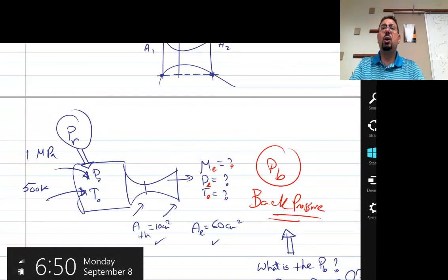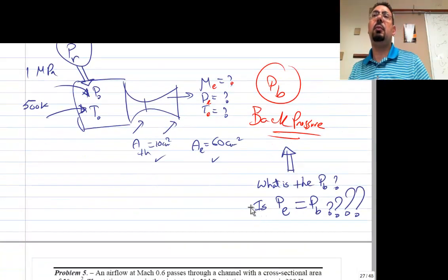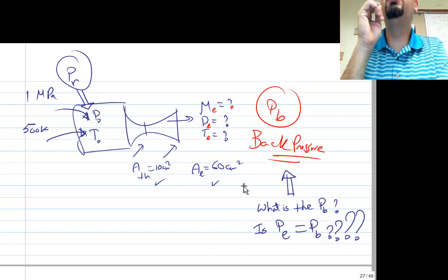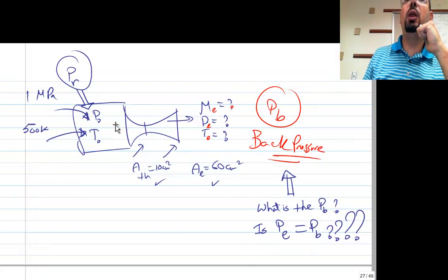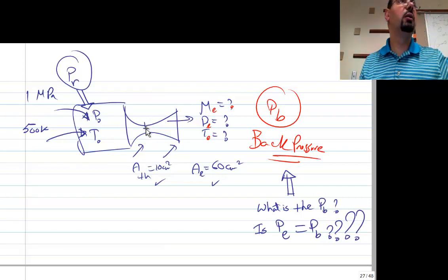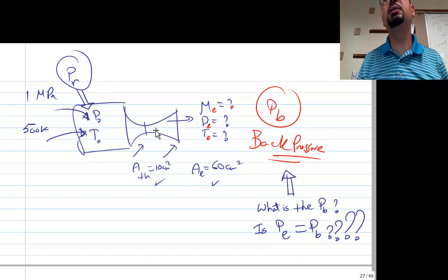Right. So again, now we know that the flow will accelerate into something like this, and once it reaches the throat, will it become subsonic and decelerate again because the area is getting bigger, or will it hit Mach number 1 and continue accelerating as a supersonic flow in this place?